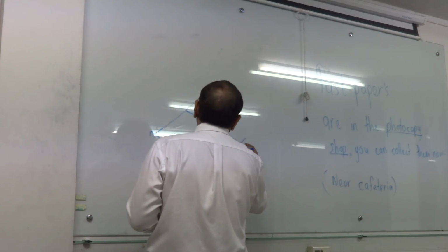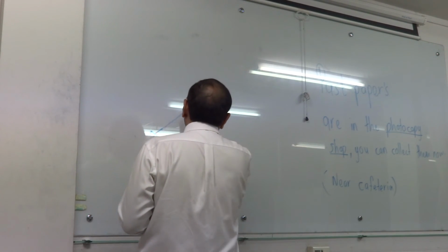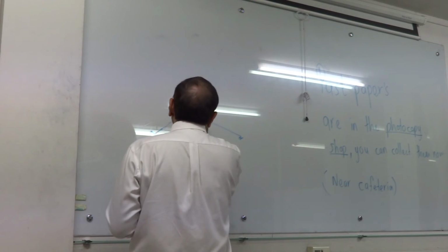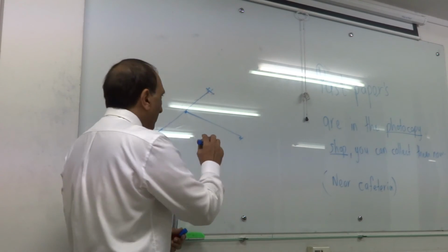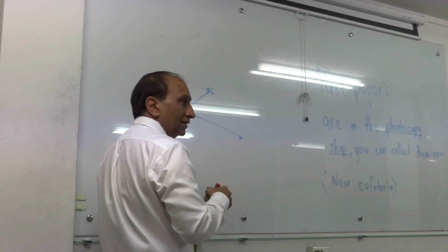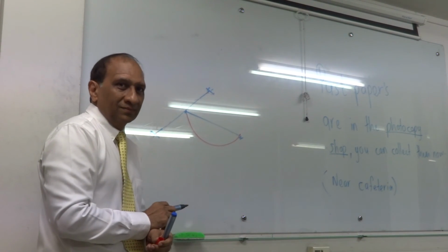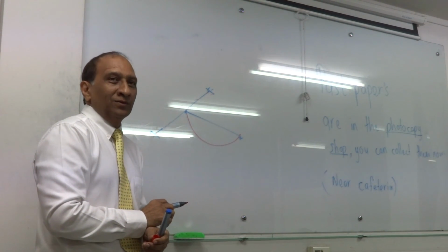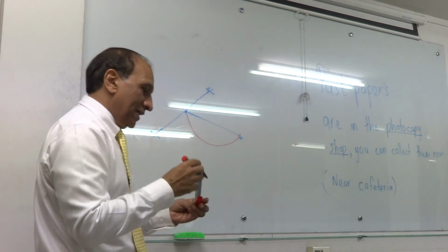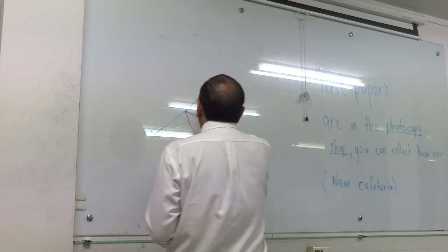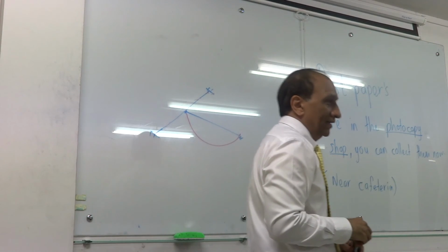Suppose that we have a beam here, and here I put a hinge, correct? If I put a hinge here, then the bending moment diagram will be like this, correct? But the beam did not fall down, it is still stable. So that is what I was saying, that even if we do not have any torsion capacity of that beam, the structure will not fail.